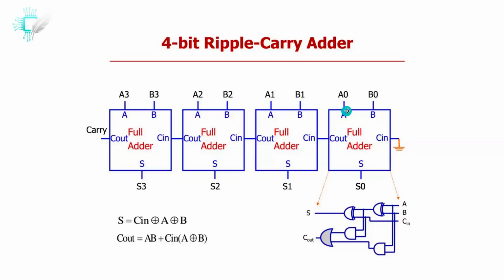I would write one full adder code over here, then again full adder code, then another full adder code, another full adder code. Basically, I would write module, input A0, input B0, input C in, output S, output C out. Then again, I would write assign S is equal to A0 XOR B0 XOR C in. That's how you write a code. But this is increasing the lines of code. Let's say here you have 7 lines, then here also 7, 7, 7; 7 fours are 28 lines of code. So it is increasing your lines of code.